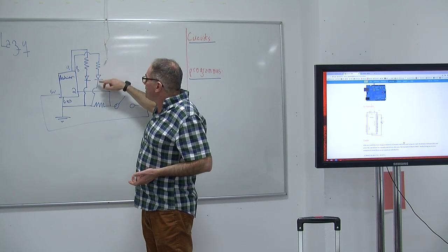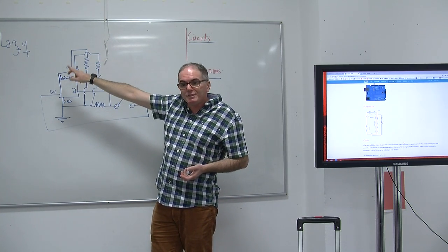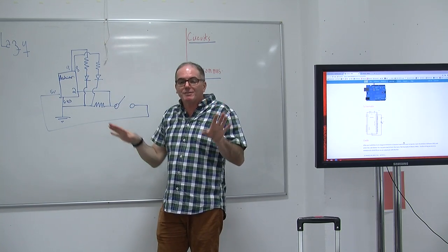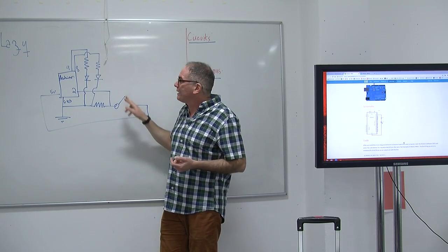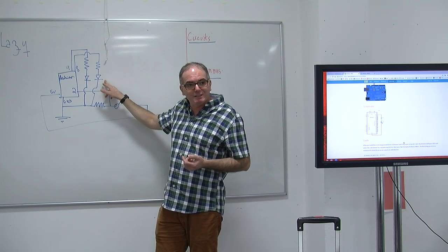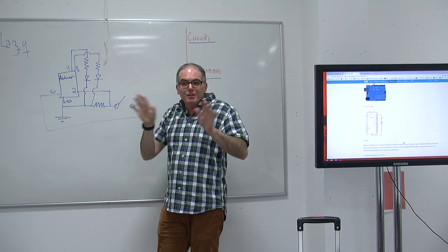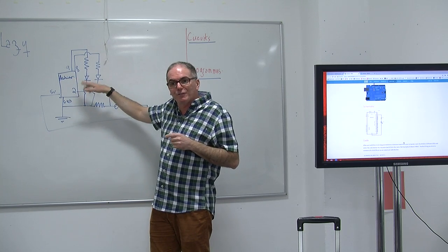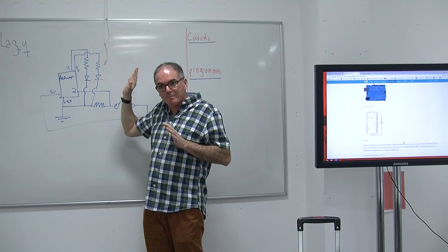Then we did another circuit exactly the same, and we put it to a different pin. We could have put it in the same pin, but then these 2 LEDs would have been like clones. They would have behaved exactly the same. We don't want that, because we want, when the button is pressed, one LED to start blinking, and when the button is not pressed, the other LED to start blinking. That means if you want to have something doing different things, the easiest way to do that is to put them in different pins, and then you say different things. The Arduino will do different things on each of the pins, okay?